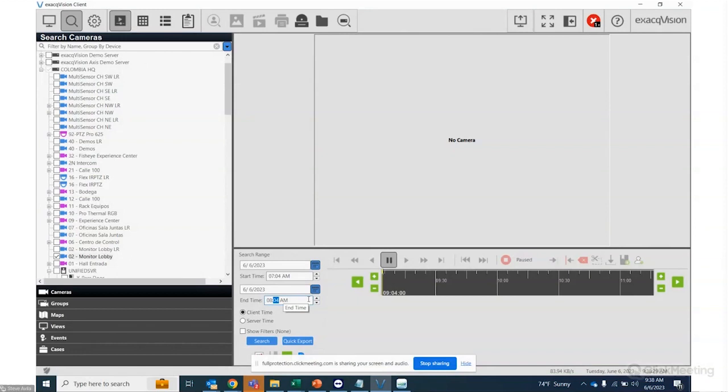When you hit the integration overview, it gives you a document that tells you what version of Kantech EntraPass they integrate with, and what version of Simplex they integrate with. So in this case, Kantech EntraPass version 7.0 integrates with the Simplex 4100 panels using the 10201 software, or the 20202. Actually, I think that's firmware. How do you connect to that panel? RS-232 to the KT or a gateway. Which controllers connect to the Simplex fire panels? KT-400s and KT-1s.